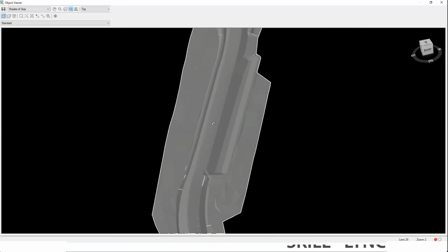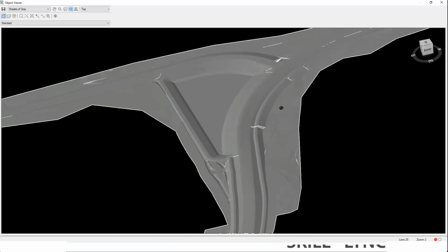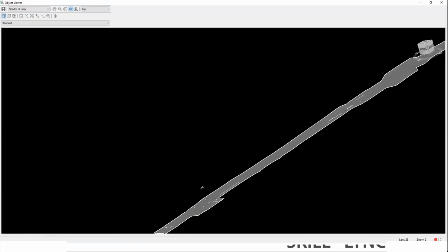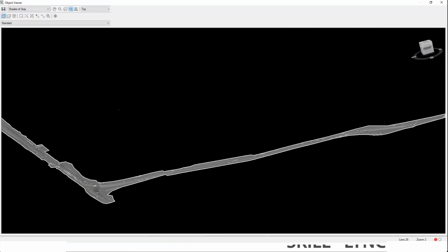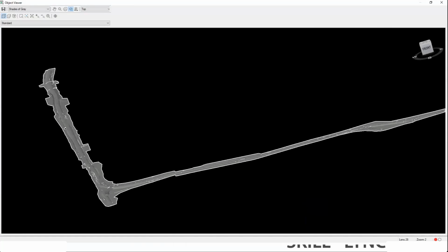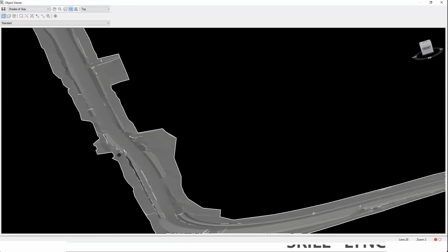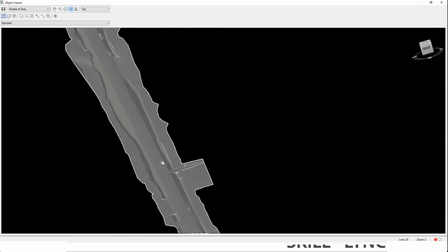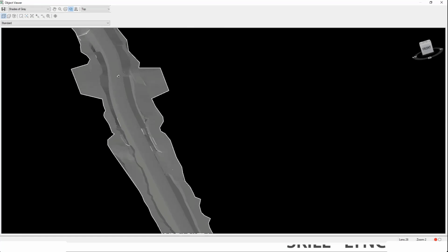Then we have some more ditches, another pond, and then this project basically just follows the existing road for the remainder. And so we don't have any ponds that go up here. But you can see that to fit the road, we're on existing, but we still are adding curves as needed. They're very large curves, so no super elevation is required.